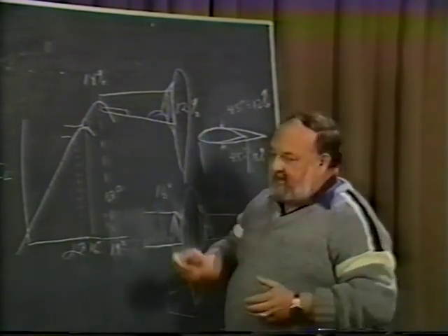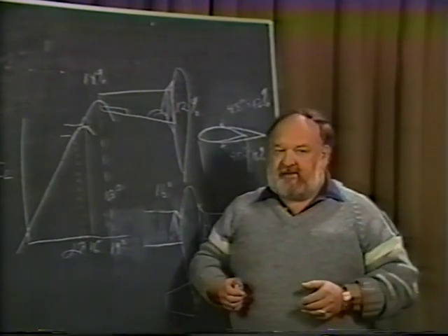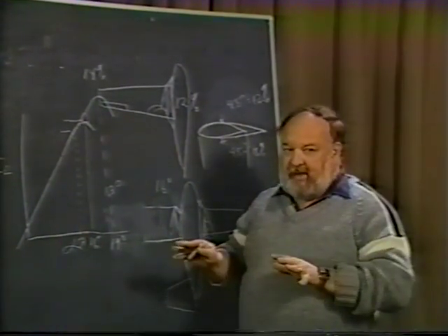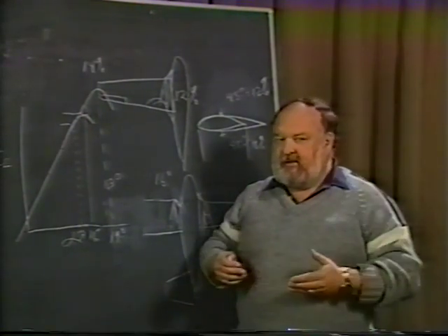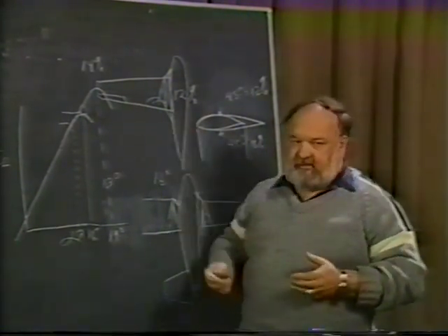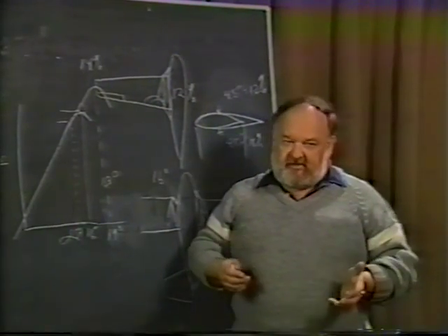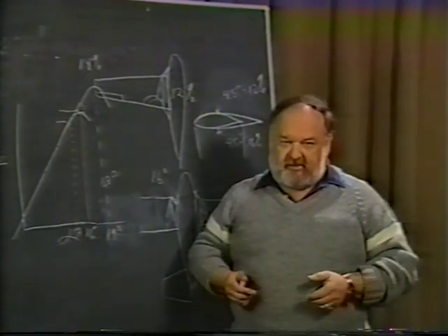One side effect of all of this is how does the airplane act in a spin? I mean, first we're talking about stall patterns, but then what happens once you really get into a spin? Well, most of the time the same things that give you good stall characteristics and good stall patterns will be the same things that will give you good spinning characteristics also.